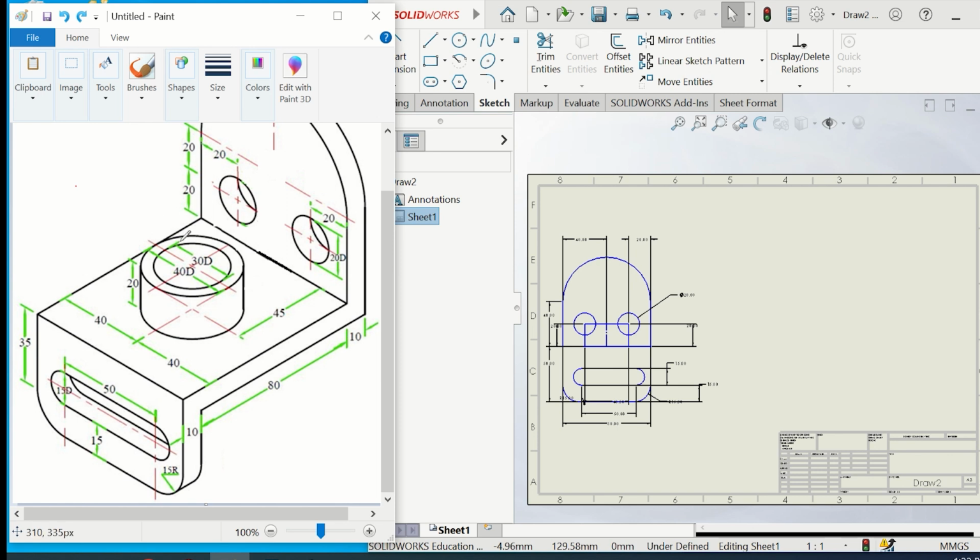So in order to represent that hole and to differentiate this cylinder from a similar part that has no hole of diameter 30 units, we need to represent that hole as existing there, though we cannot see it from the front view. This hole is a cylinder, and when you look at a cylinder from the side, it appears as a rectangle. Same as the bigger rectangle of the two, which had 40 units of width and 20 units of height.